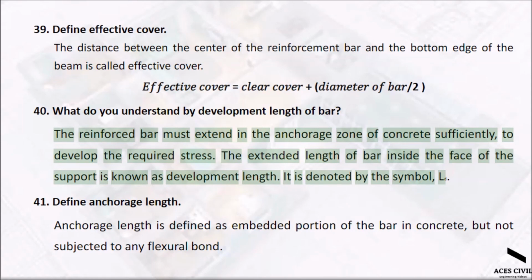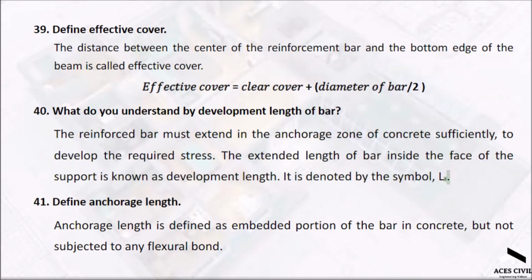The extended length of bar inside the face of the support is known as development length. It is denoted by the symbol Ld. Define anchorage length. Anchorage length is defined as the embedded portion of the bar in concrete, but not subjected to any flexural bond.